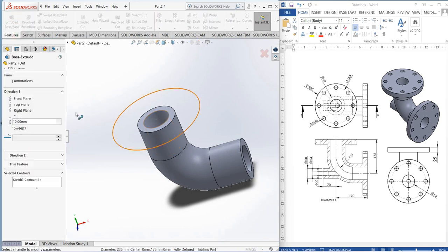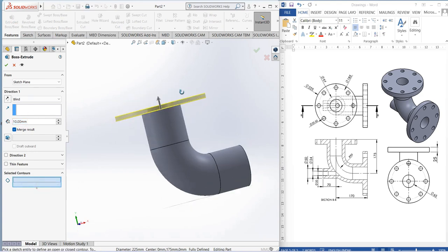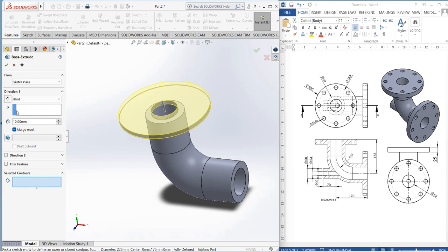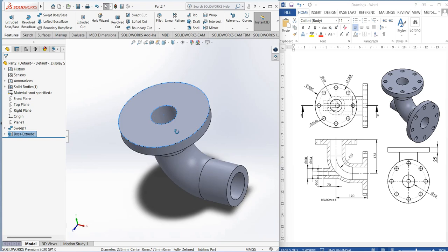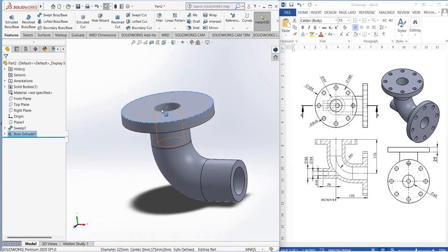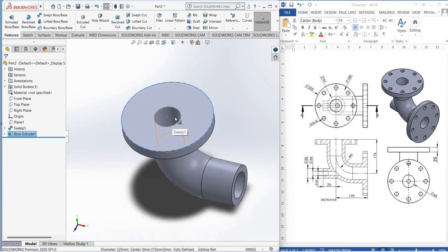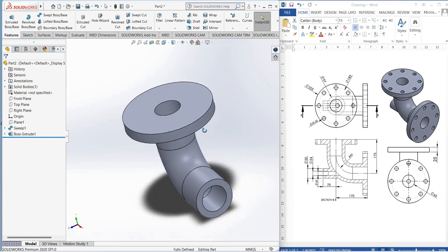Now what we do, we will click on this circle, yes, like this, because it is selecting contours. We don't need contours. And inward direction and distance is 25. If we don't select this circle, what will happen is this area will be filled. Okay, you already know that, right?